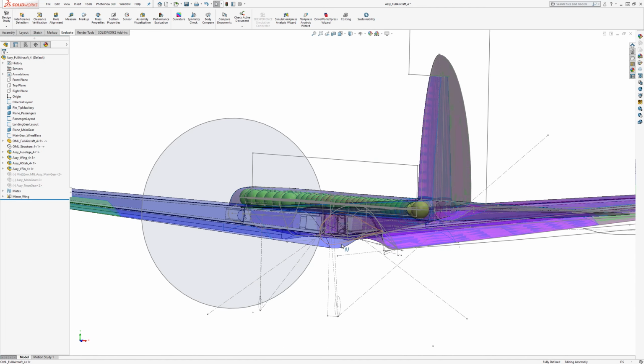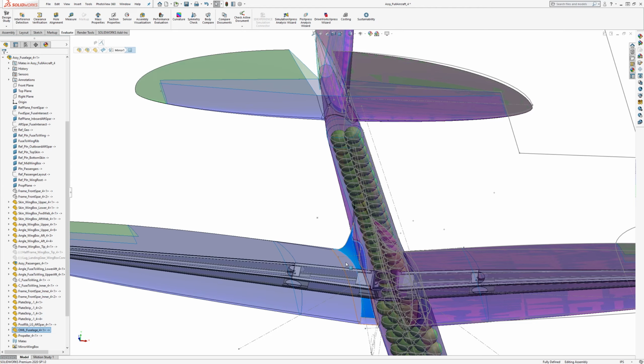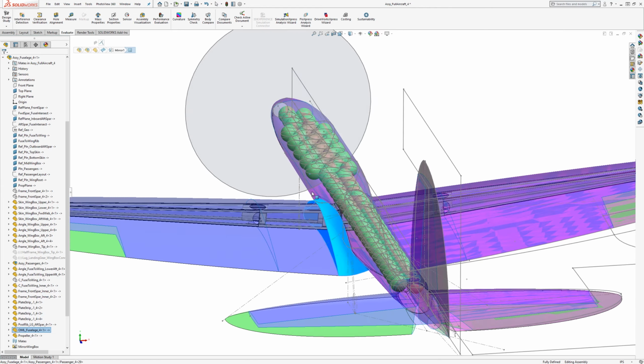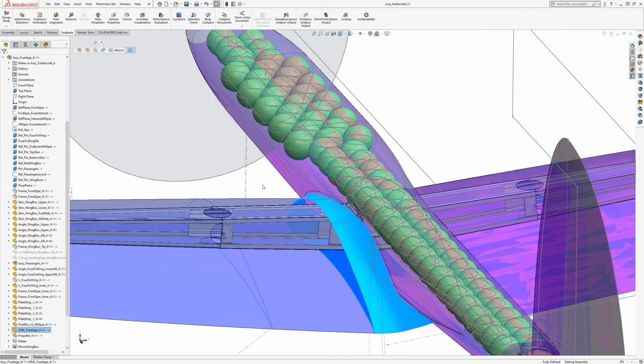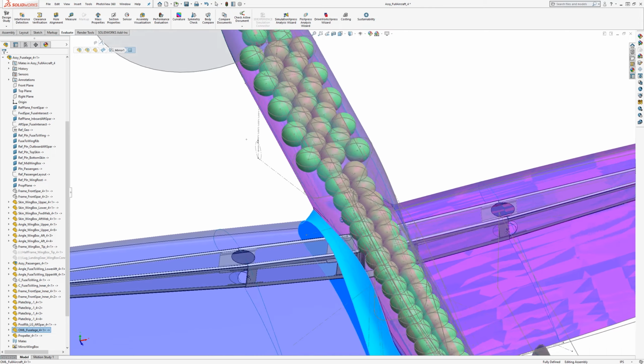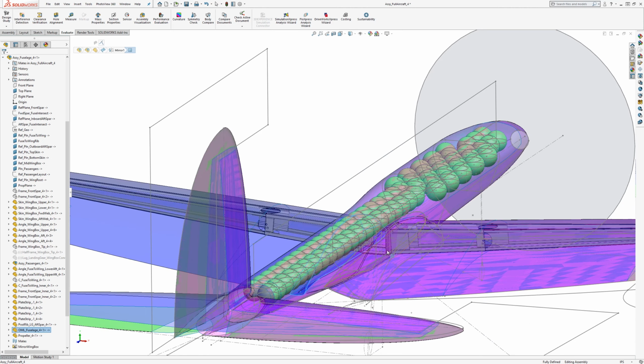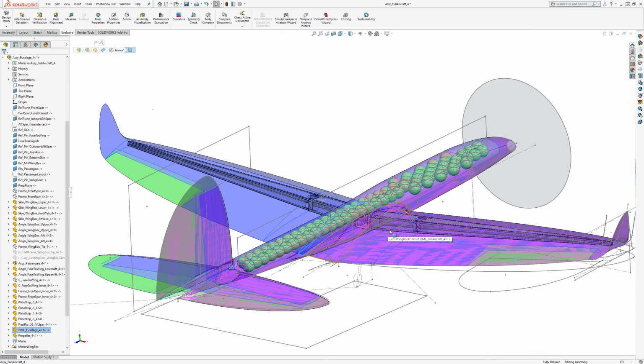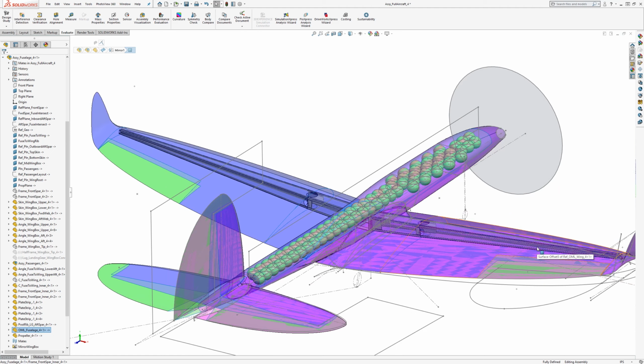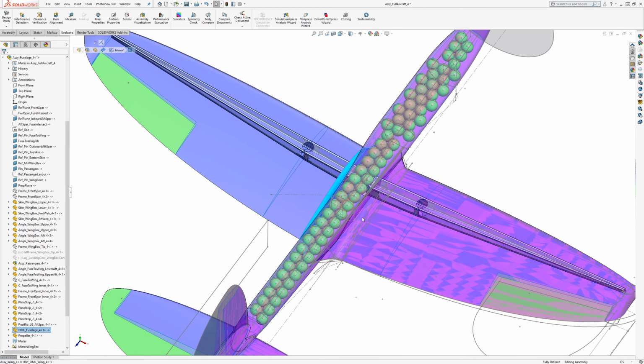That's an area where there's a smoothing of the interaction between the wing coming in and the fuselage, both in terms of the aerodynamics, and also this area is often the most complicated portion of any aircraft, just because it's also where the highest loads are, and where loads are coming in from the direction of the wing and also from the fuselage.